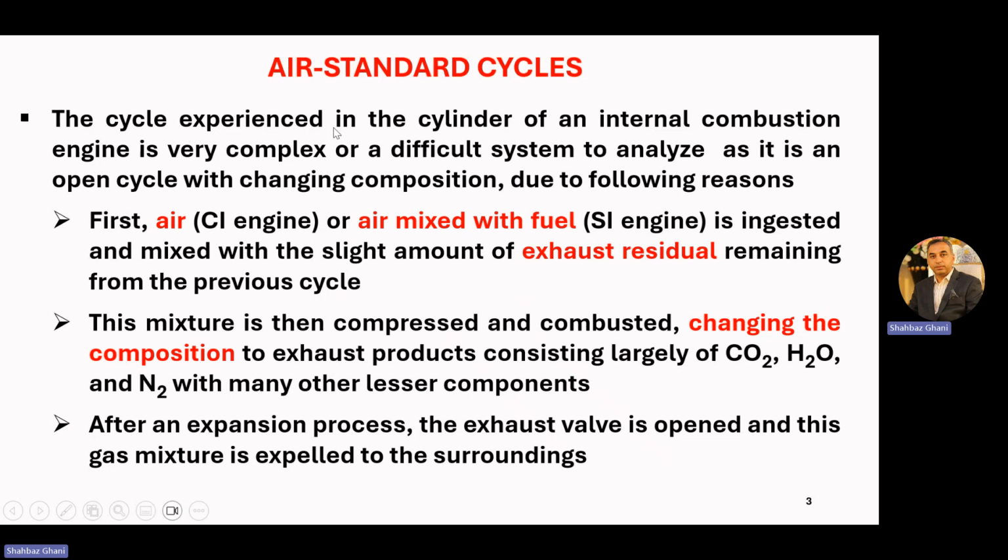The cycle experienced in a cylinder of an internal combustion engine is a very complex, difficult system to analyze, as it is an open cycle with changing composition, due to the following reasons. Number one, first air in CI engines, the compression ignition engines, or air mixed with fuel in SI engines, the spark ignition engines, is ingested and mixed with the slight amount of exhaust residue remaining from the previous cycle. So the air which we are injecting inside the combustion chamber, or the air-fuel mixture which we are freshly inducing inside the combustion chamber, is mixed with the exhaust residue of the previous cycle.